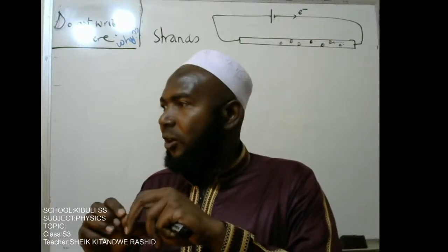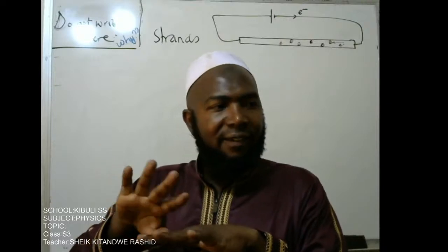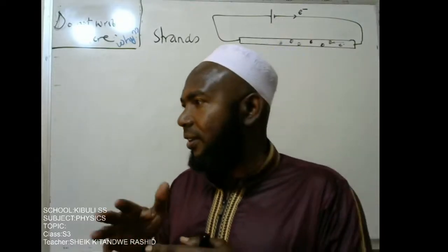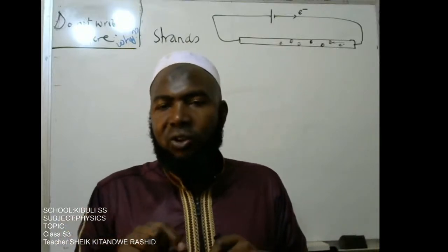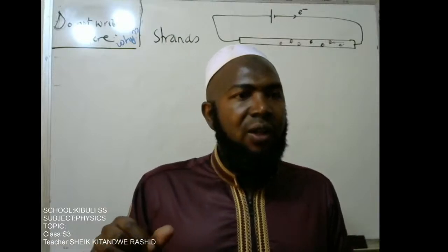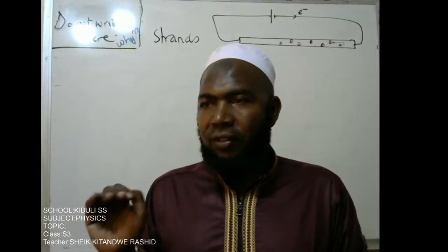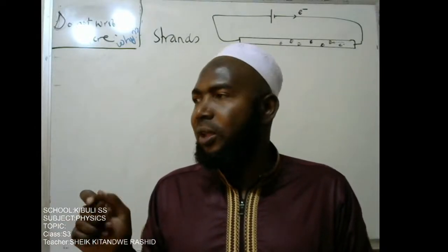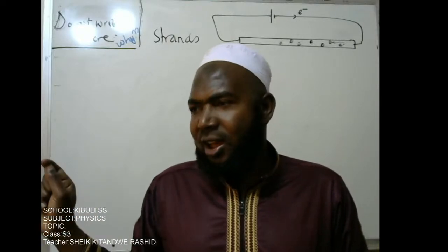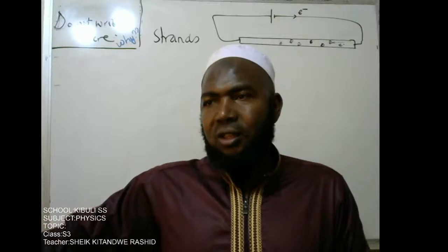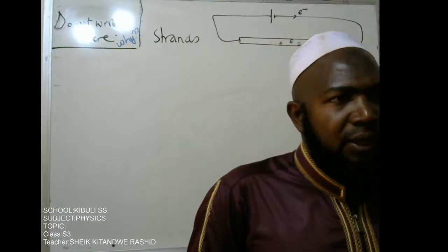Now, you see these connecting wires can have strands. They are like loose connections that may connect and then conduct current. So those can cause electric shock in the casing of the appliance. So what we normally do is earth the casing of the appliance so that any stray current is directly connected to the earth, so that the casing is at zero potential and therefore cannot cause electric shock.